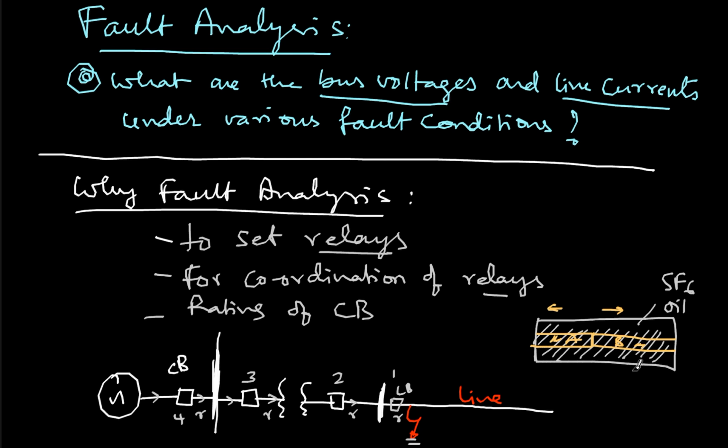But suddenly if the fault current comes 20,000 amperes, the moment it tries to disconnect, the entire circuit breaker itself will blast, and it causes more fire, and that oil which is there spills the fire to the nearby equipment and keeps on spreading it that way. So we need to know how much is the expected fault current value in order to decide the circuit breaker rating.